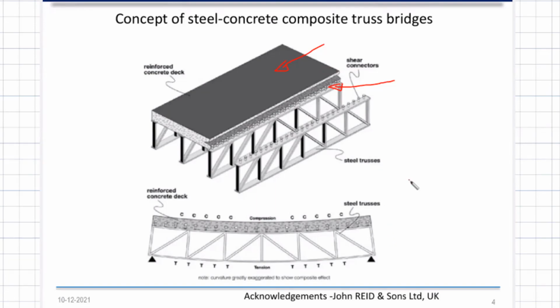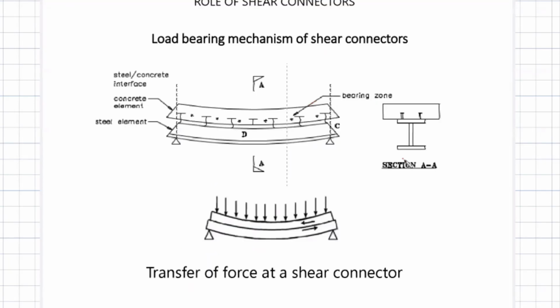So I have given you a brief of steel concrete composite systems, in which two different materials, both good in some respects, are integrated using what is called the shear connection. With that introduction, I will go on to show you the chicken coming before the egg, or something. I want to say the shear rigidity of the system is going to dictate how a steel concrete composite system behaves together.